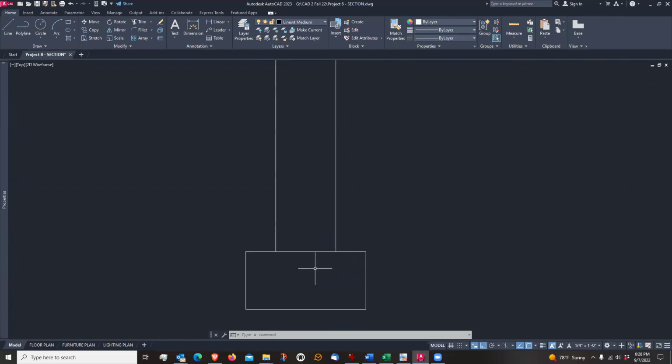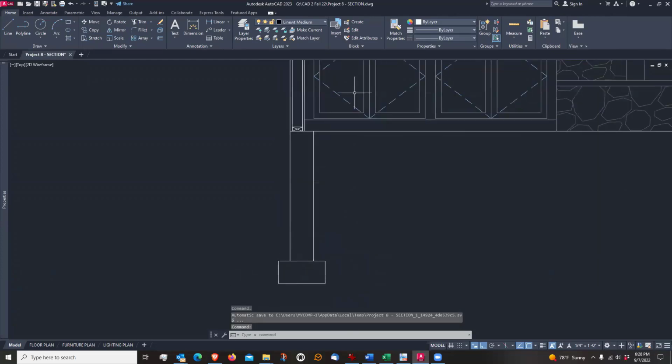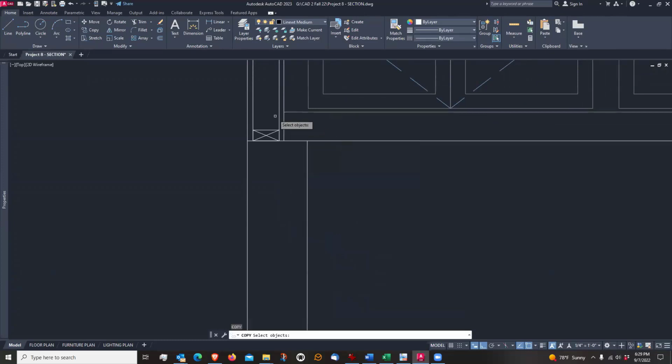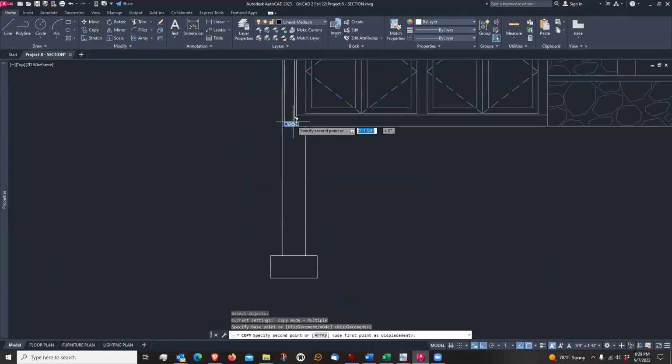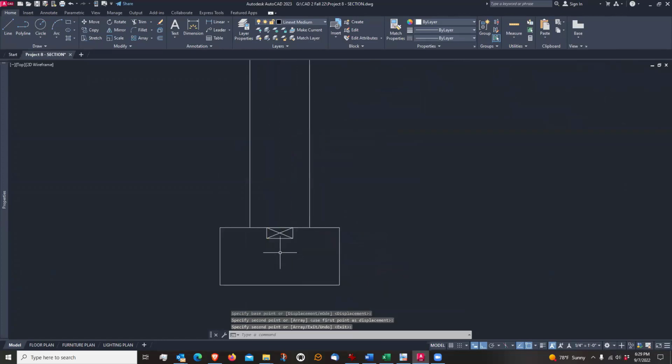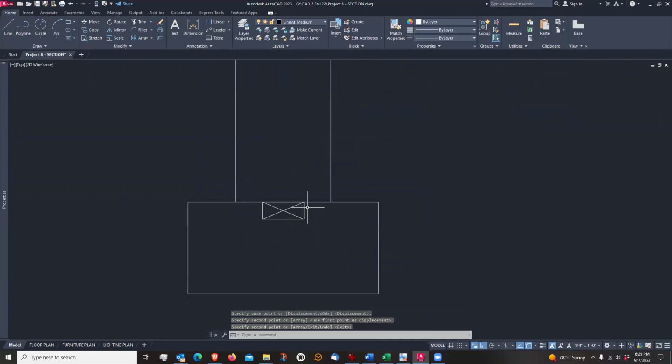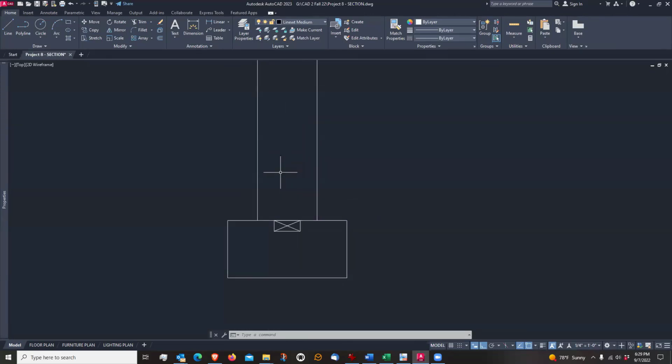And the way that the contractor does it is when he's pouring the footing, so he has the forms all set for the footing, and then they pour and fill this with concrete, and it's wet concrete, and then they embed into the concrete. They embed a stud right into the concrete, and then they let the concrete dry, and this stud is sitting in here, and then they pry it out, and then there is this rectangular keyway that's left over, and then they pour the foundation wall.